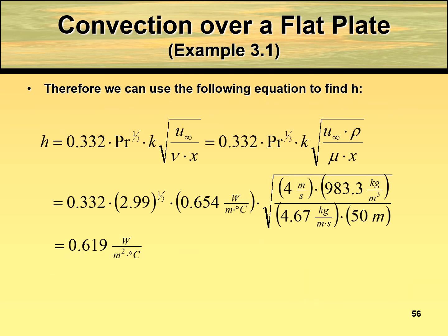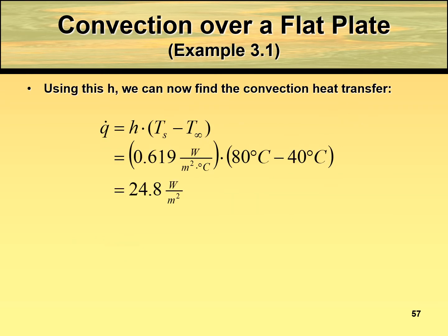Okay, so you can apply the equation that we derived before, for 1/4 and as well for the entire flat plate. Then you have the H value, then you can calculate the heat flux for the flat plate or the rate of heat transfer in the convection conditions, which gives you 34.8 watt over meter square.